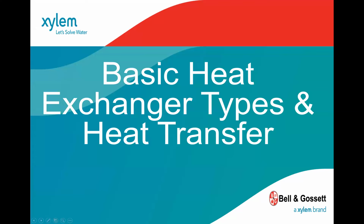This is one of the more basic. So you might hear somebody say, all right, 500, so if someone says it's 100,000 BTUs and they're looking at a 20-degree delta, you have a lot of people that might say, 500 multiplied by the delta multiplied by the GPM gives you those BTUs an hour.